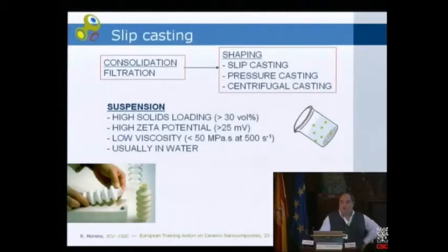And the advantage is that usually we perform slip casting in water, but we can also do the same in organic solvents. In this case, to consider the stability of the particles, we must consider that the surface charge is much lower due to the lower dielectric constant of the organic liquids, so we need to increase the surface potential at least 2 times over that in water.